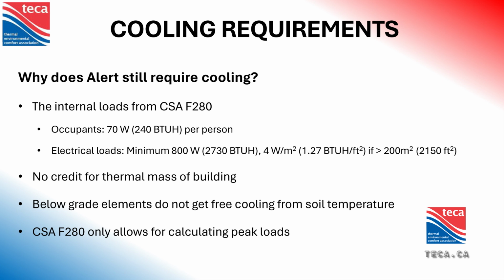The below grade elements, radiation pulling heat off of you has a huge cooling effect. You don't get credit for any of that either. Because all CSA F280 is going to do is provide you a peak load. And you might ask, why? Like, that seems weird. Why would it do that? Because that's what it was designed to do. It was never designed to answer this question of, is cooling required, yes or no?